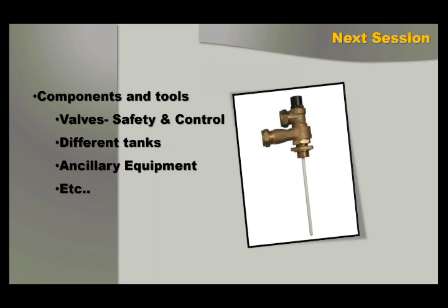There are aftermarket mechanisms that one could buy. There's a controller with a dump valve function that controls a solenoid valve. It measures the temperature of the system, and when it gets to a certain threshold, it opens up and effectively dumps the hot water before the TP valve has to start dumping it. So it protects the TP valve and the system, because the temperature threshold will be a lot lower than your 94 or whatever degrees it is that your TP valve is rated for.